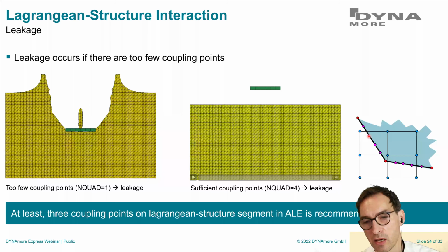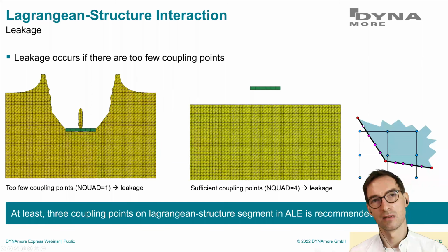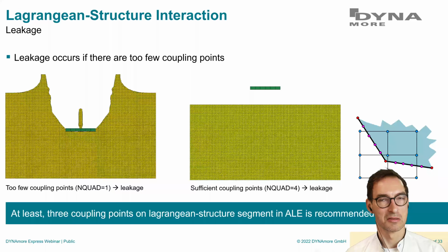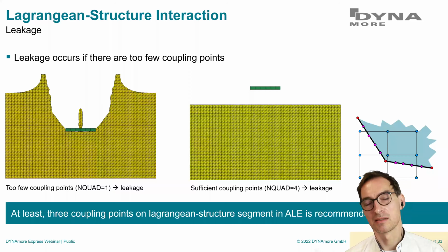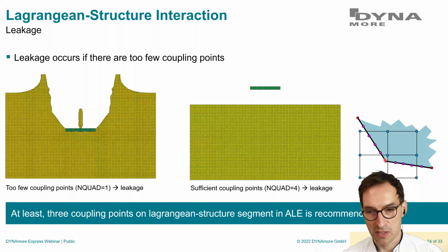And that way you have a couple of coupling points inside each ALE element. Yeah, so for this, you could mesh an element here, here, here, here. But if you do explicit, then you have smaller mesh sizes, then you have smaller time steps and so on. So I think maybe this is not that straightforward. But what you can do instead is you can introduce more coupling points. Yeah? Instead of having a finer mesh, you just keep this mesh, you can introduce more coupling points.